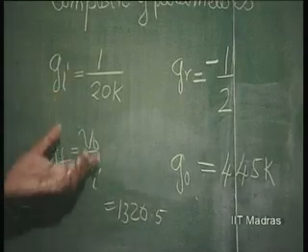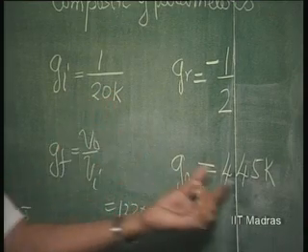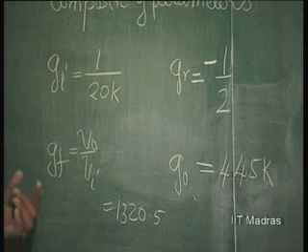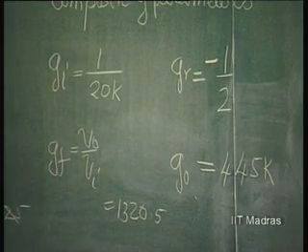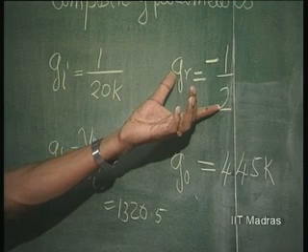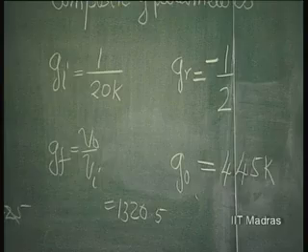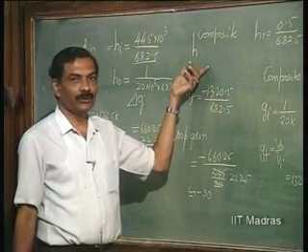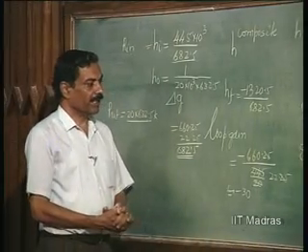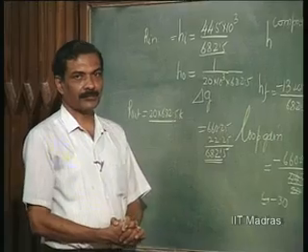In this case, it is decreasing by what factor? 1 plus loop gain. 20 K divided by 31. 445 K gets boosted up by 31. This particular thing, originally we had this feedback factor of half. So, now the forward transfer parameter is going to be very nearly equal to 2, 1 over the feedback factor. So, these are the modifications that take place in the case of feedback.